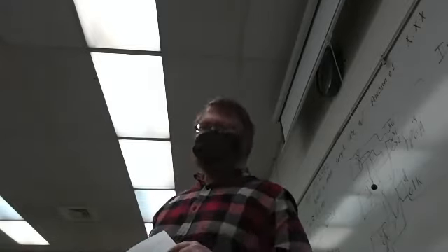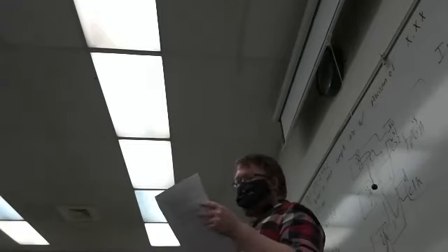Okay, so just go off based on, we want to sample the data in the middle, so just go off what happens in the middle. Yes. So CPOL equal to 1 is rising edge. Okay, thank you.